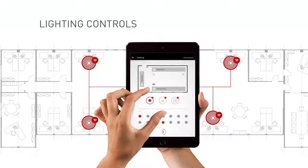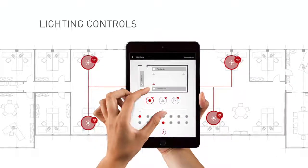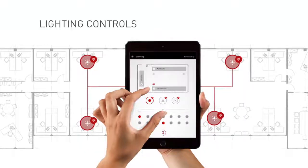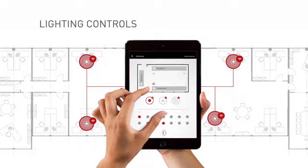And of course, lighting controls will also achieve the same result if daylight linking is included. For instance, if you are monitoring the light output that's received on your task, then the light levels will stay at the set amount over the life of the installation, but the wattage will increase over time.